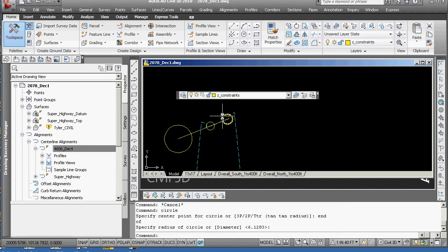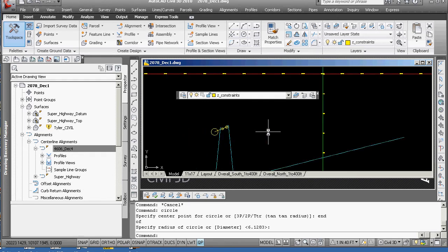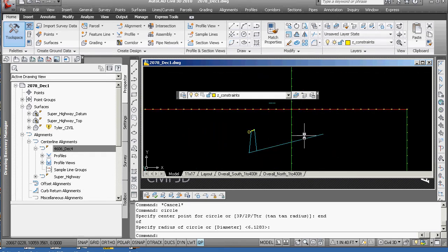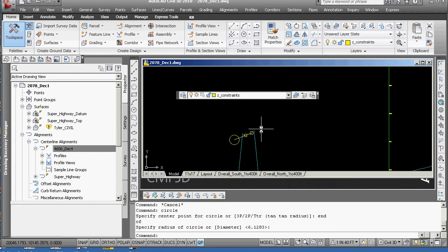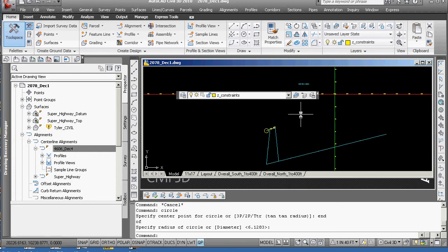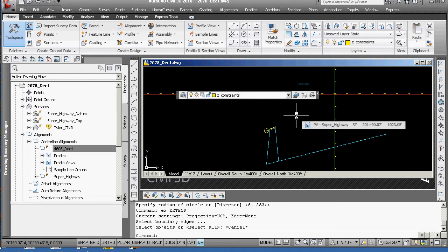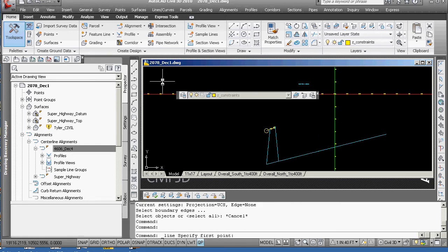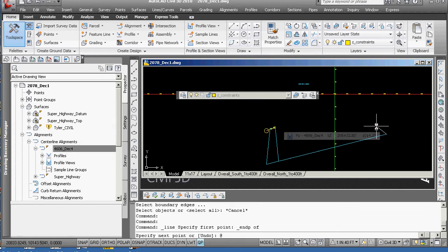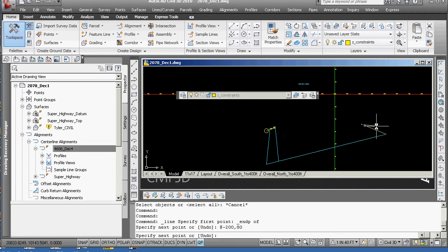These you can leave around. You can probably get rid of that, and in the end you also might want to come back down to that one. So for now we're going to go ahead and just extend, kind of think about drafting this. You can start thinking about not wanting to be less than 4%, perhaps in a design like this. So you can go to the end point here, a line from the end point here, and you can say now at minus 200, and you want to go up at 4%, that would be 8 or 80, so 80. So that gets you a general sense there. That's 4%, so that's actually not too bad.